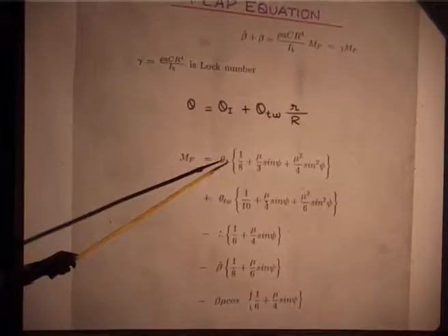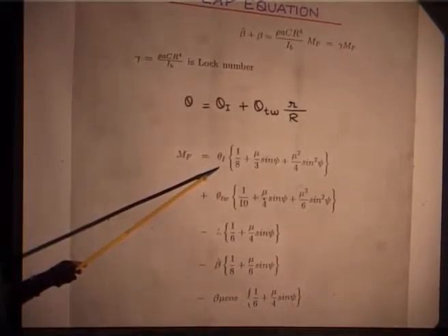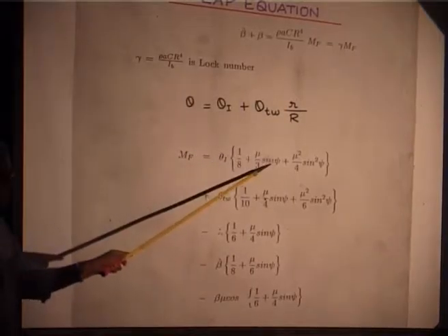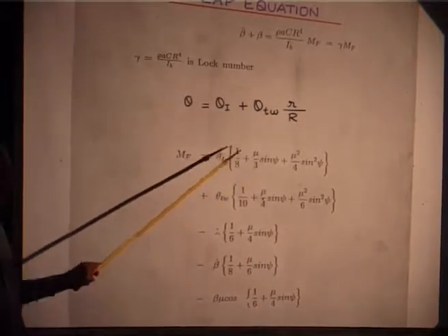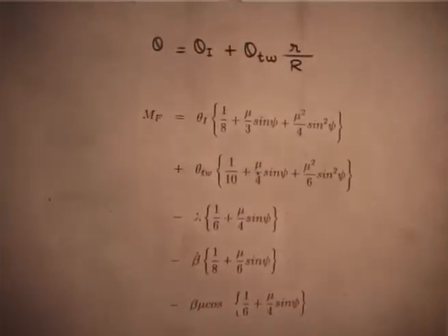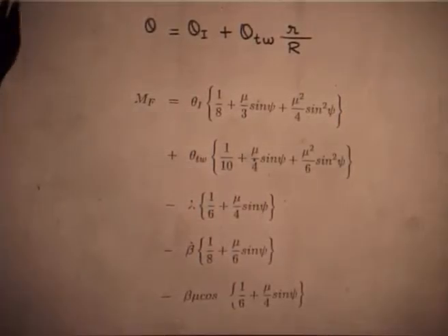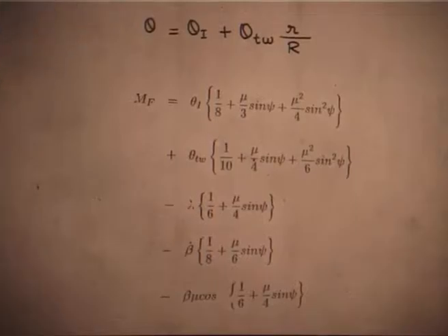If I put theta I equals theta naught plus theta 1c cosine psi plus theta 1s sin psi, this is getting multiplied with another sin psi, getting multiplied with sin square. That means I have second harmonic, third harmonic, everything comes as an input. So my response also will have all the harmonics.